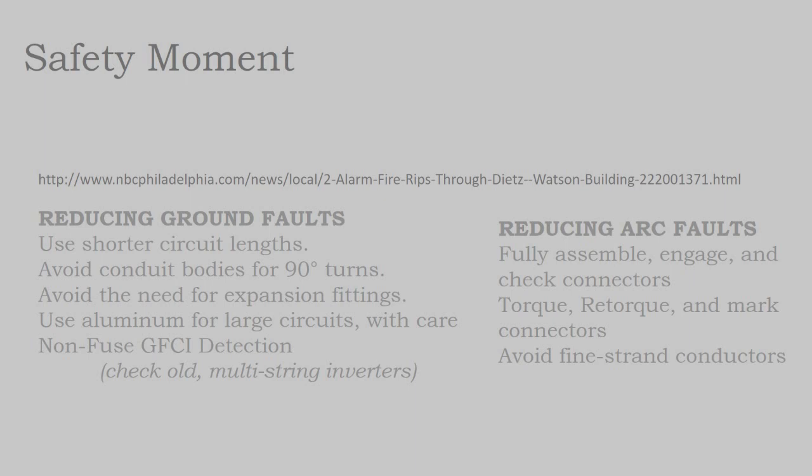There's fire code that says on commercial buildings every 150 feet you've got to put a walkway for fireman access. And then you think, well, if I'm using a forced ventilation system, do I need to do that? Well, there's other reasons why rooftop clearance requirements on your solar array are worthwhile.